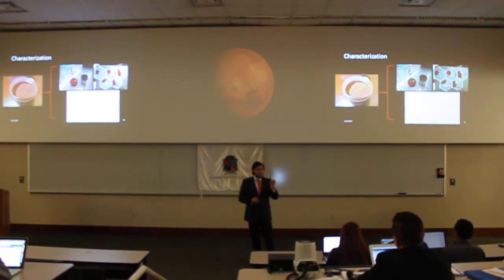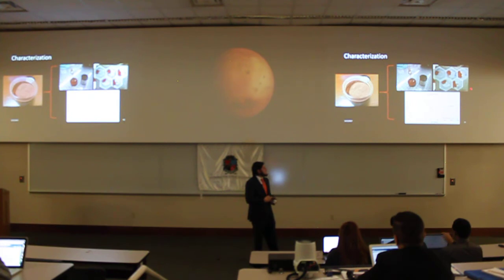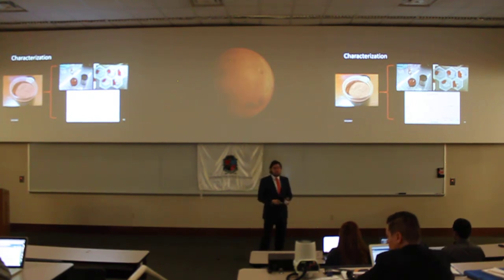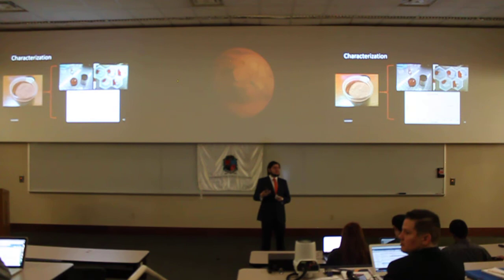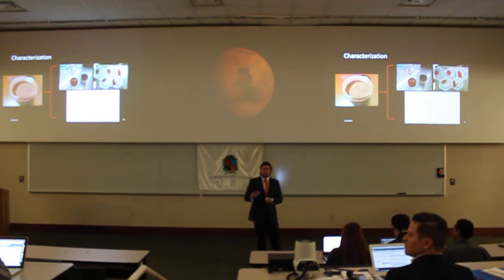So we ran a characterization in several terms. We measured its density, the particle size distribution, and its behavior when mixed with water. From this point, we started to work on the mix design of another process that will allow us to build infrastructure with this.